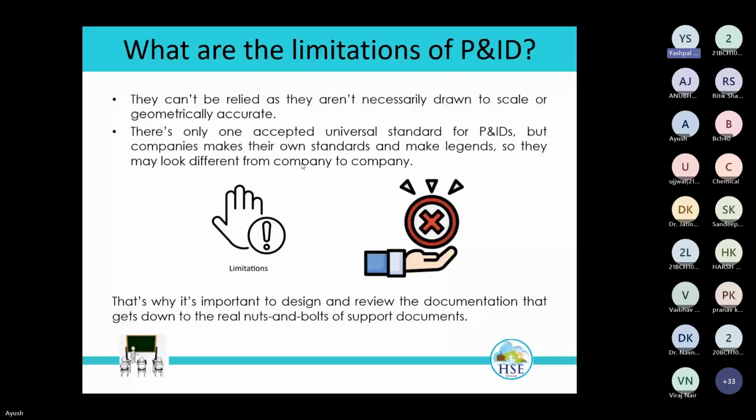We just represent that we are connecting two equipment with the piping, or we can have the size of the piping, and MOC also, various other things like whether insulation is provided or not provided, the purpose, or the piping used for different fluids, so the fluid name also. So that can be there, but we can't have the actual length of the piping in the P&ID, or the actual size of the equipment.